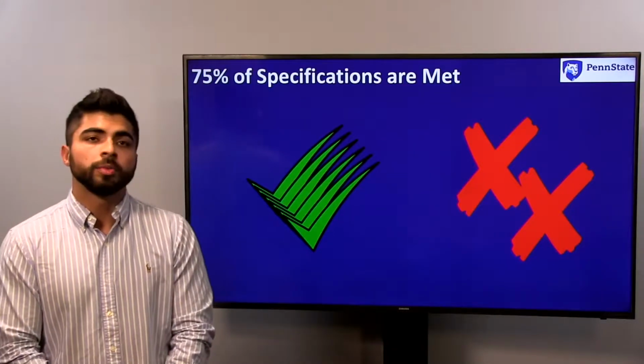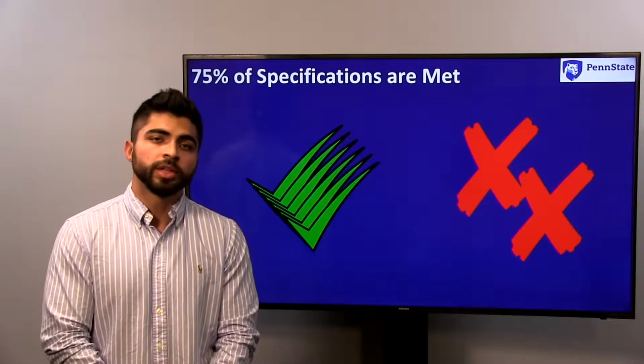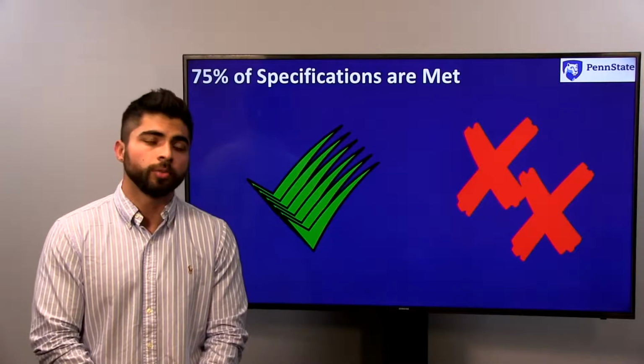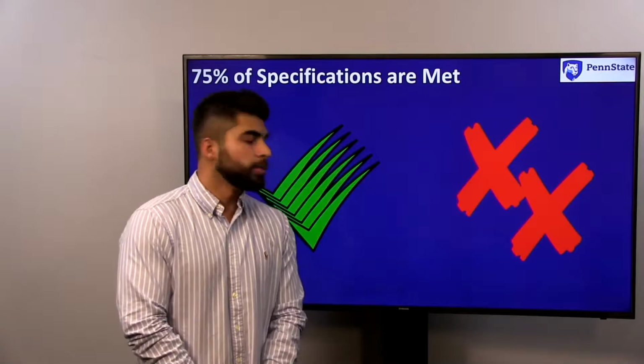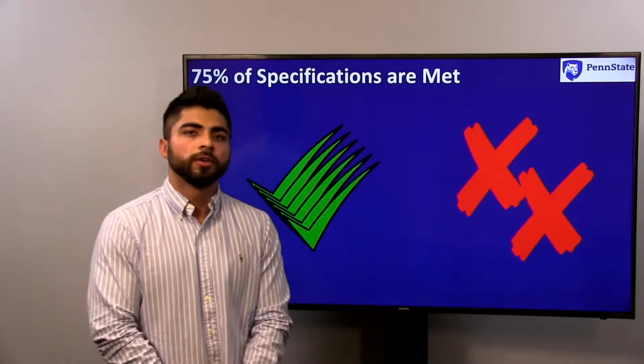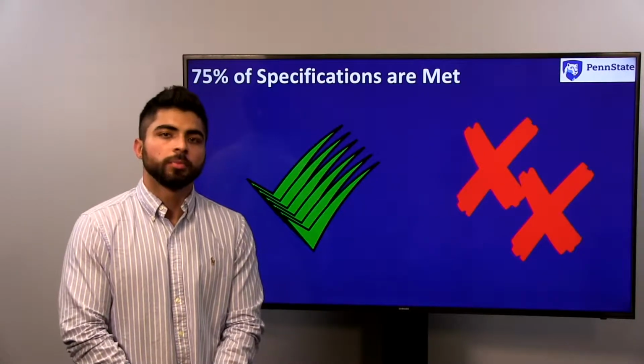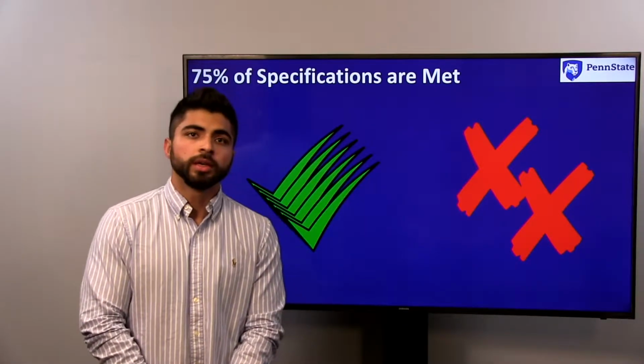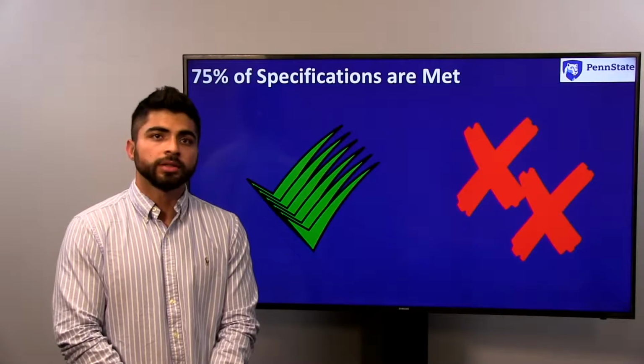The reason behind that could be because we had to adjust the flow rates for the streams, as we used a decanter to separate diethylbenzene from water. Another spec we couldn't meet was the recoverable vinyl cyclohexene as a product. The reason behind that is because we did not use a recycle stream for the second reactor.